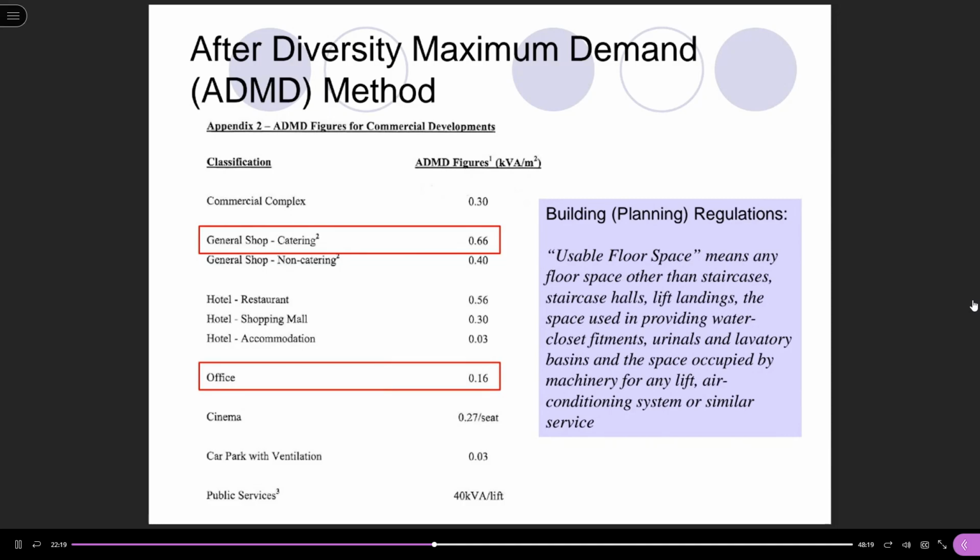Okay, so generally, the power density for office will apply to the office area. The office area by the tenants, excluding the lift lobby, the circulation area, the corridor, and the toilets, and so on. All right? So in the mini design project, I will give you an office layout plan, and you need to estimate the total building electrical load for that building. So make sure by that time, when you estimate the area and apply these loading density values, don't include the area of this space. Okay?